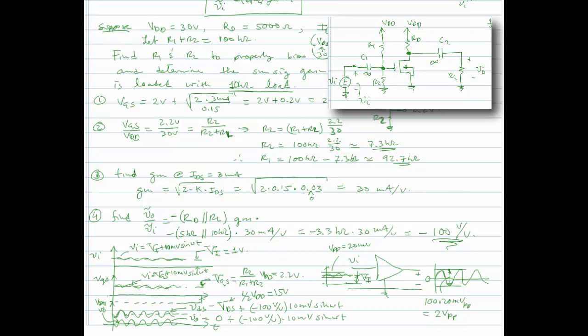Similarly, the DC blocking capacitor C2 at the output prevents any of the offset at the drain from ever reaching the load resistance. And so regardless of where you were to bias the drain voltage, here we've done it at 1/2 of VDD, regardless of where that is, the bias point for VO is always 0 because of the coupling capacitor, or DC decoupling capacitor C2 at the output.